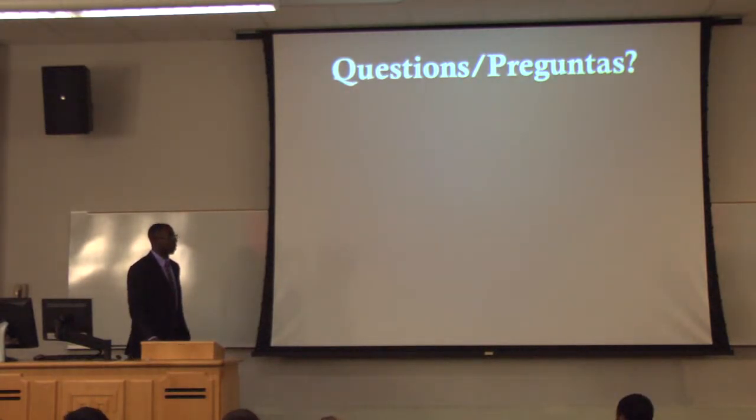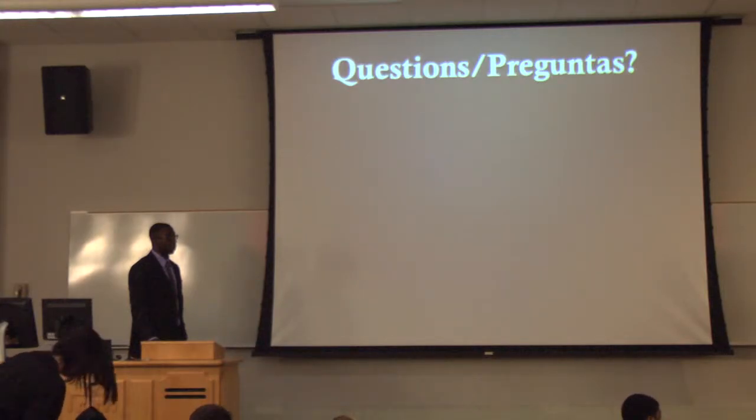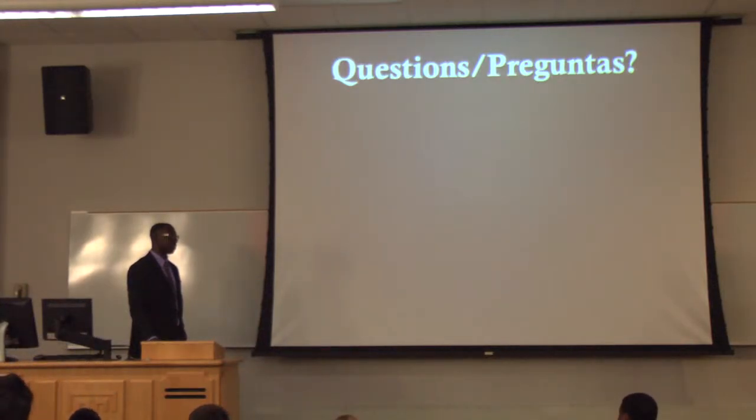That's a high flow, and it may actually break down the pump running for 24 hours. It's not really running 24 hours. How long is it running? Well, on the slide that we have, it'll be running for 11 minutes every hour. So in these 11 minutes you have to pump 112 gallons? No, we pump the full volume of our stock tank to our grow bags.